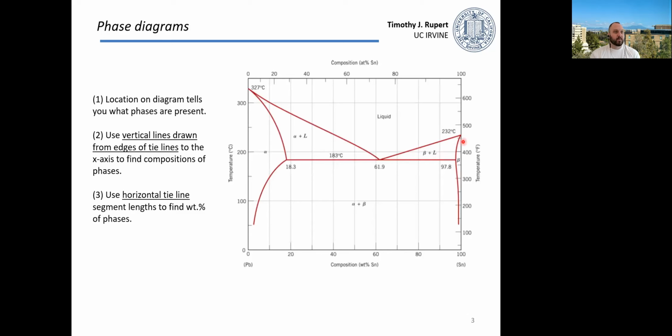All right, so just a brief reminder about phase diagrams. These are very powerful tools. They tell us the equilibrium state of different material systems for a given set of thermodynamic conditions. Most common in material science and really in engineering materials, you're going to see these often shown as things like temperature on one axis, composition on the other. But be aware that that doesn't necessarily have to be true. You could find maps that show temperature and pressure changing, composition and pressure, magnetic field, other types of thermodynamic variables. In any case, what's shown on here can be very powerful.